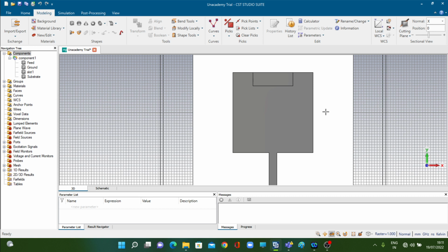Now I mentioned to you that for high frequency applications, the current is mostly, in fact, very much concentrated on the peripheral edges. So if the current starts from here and has to move around this patch, what is the total length which the current will travel? See, 30 here, 30 here, approximately 30 here and 30 here. So 120 millimeter approximately. That will give us a particular bandwidth.